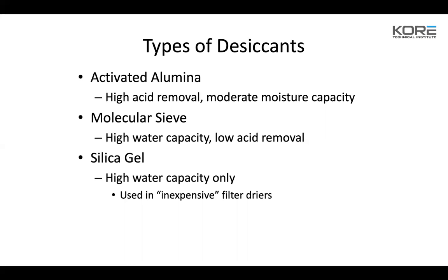What you want to do is run that high acid dryer in that system for 3 or 4 days, then come and test again, and swap them out again if you need to, then run it for a couple more days and test the system again. You're going to be testing the oil for acid. So just get one of those phase 3 oil tests and test that oil. Once you've got it to where you're not testing positive for acid, you're going to want to pull that filter dryer out of there and replace it with a regular filter dryer. Once that's done, you should be good.